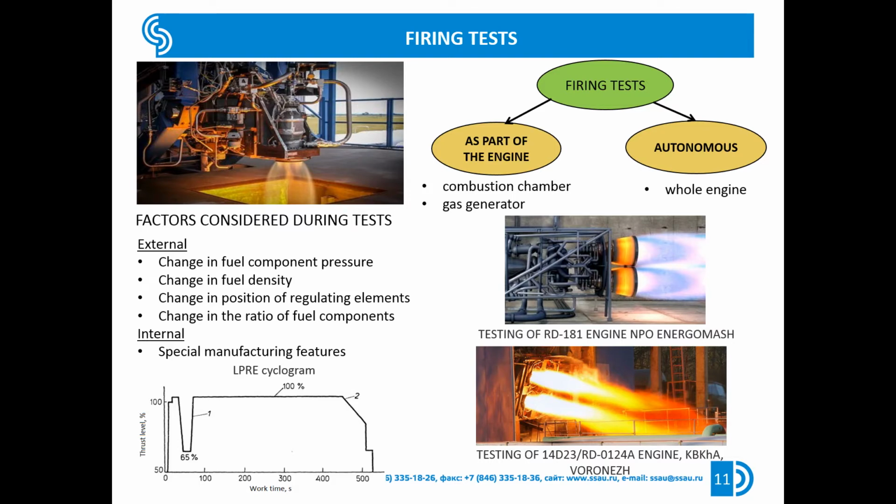Internal factors are commonly identified as physical effects on the operating mode of the LPRE, which are caused by the specifics of the construction process. They arise due to deviations within manufacturing tolerances in the dimensions or shapes of parts, which ultimately lead to a variation in the characteristics of the units.